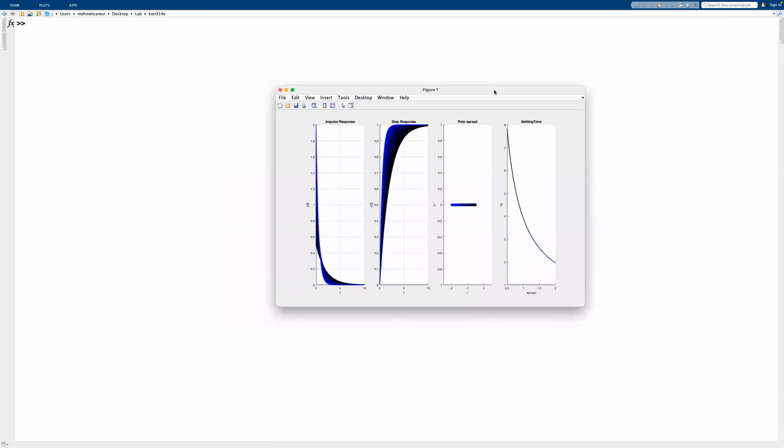Now, obviously, we can see that we start with the dark one here at 0.5, and we go up to 2, and the system becomes faster and faster, because when we draw a 2% line from 98, you can see it enters earlier and earlier, and it becomes basically faster.